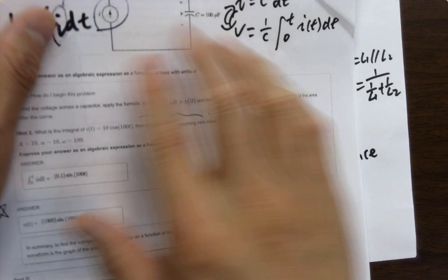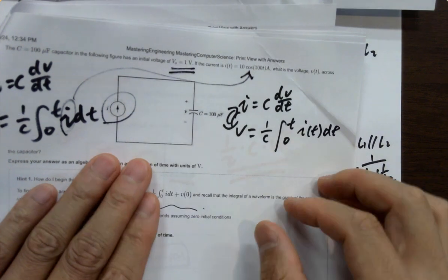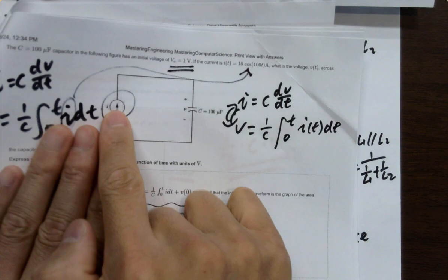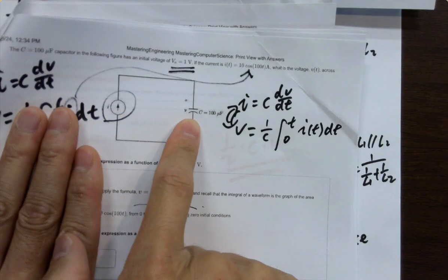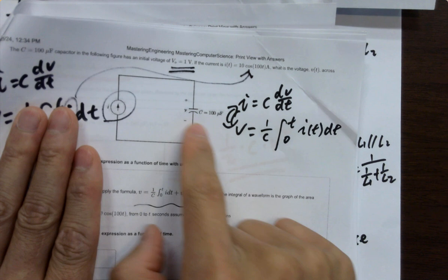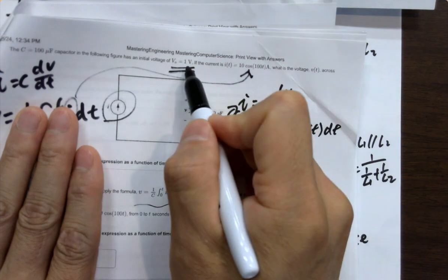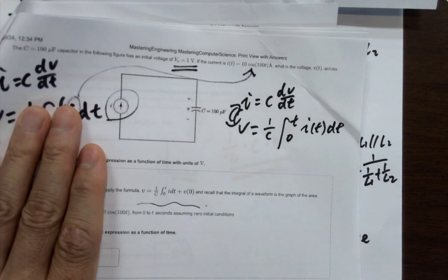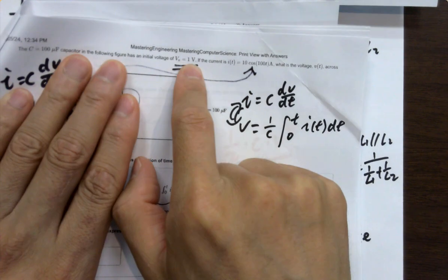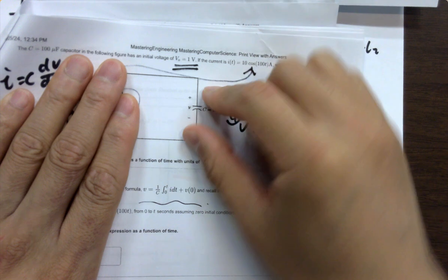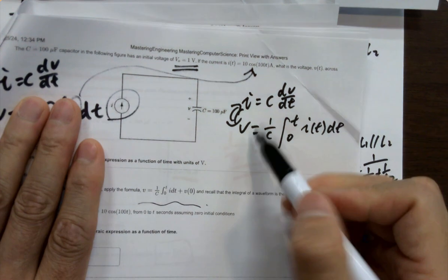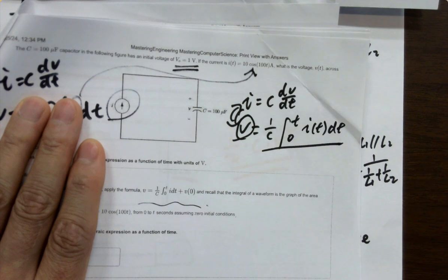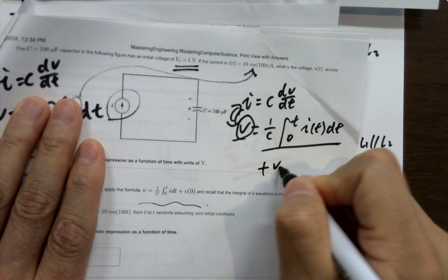Since I told you on Monday, you should always treat the capacitor as a bucket, a water bucket. You are filling the bucket with water using a hose, right? You are filling it up. So this is basically a hose, filling water into the bucket. Okay? So it has an initial voltage, which is 1 volt being stored in the cap. The capacitor is able to store charges. So it's initially stored 1 volt across the 2 plates, and then you start dumping current into it. So it's going to follow this equation for the voltage accumulated beyond that initial voltage. So eventually you are adding this to V0.